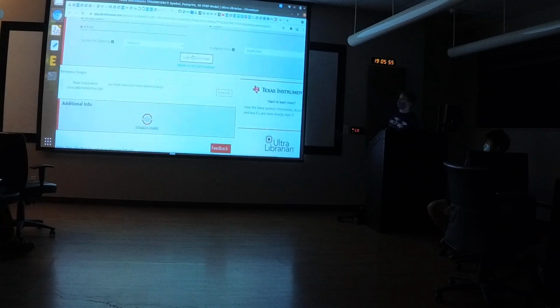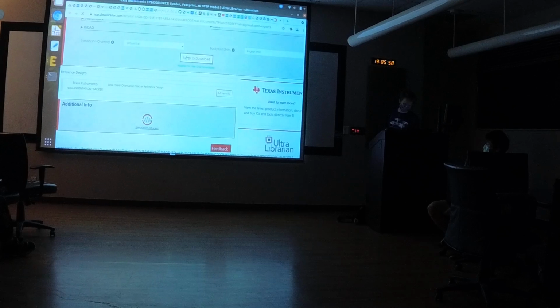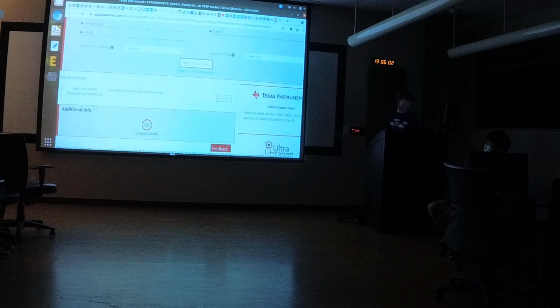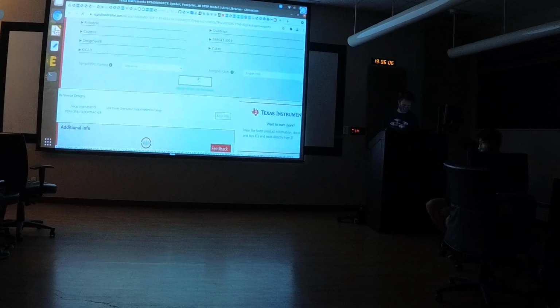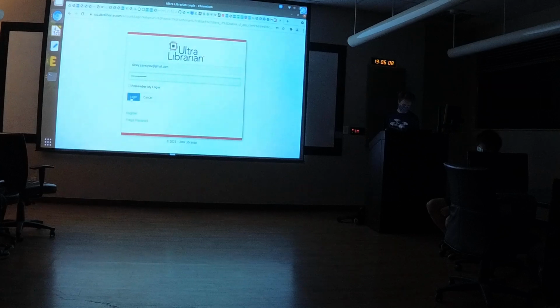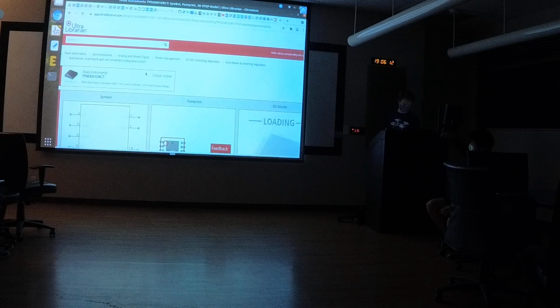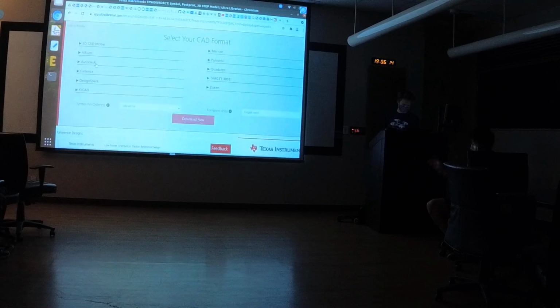You do need to create an account, but they don't ask for credit card information or anything. Most of these aren't crazy sus. They're okay to use. I think SnapEDA is good. And then we link more in the lab, yeah. If you can't find one on DigiKey itself, just go on the individual websites and then search for the part. Almost all the time, you'll see something like that.